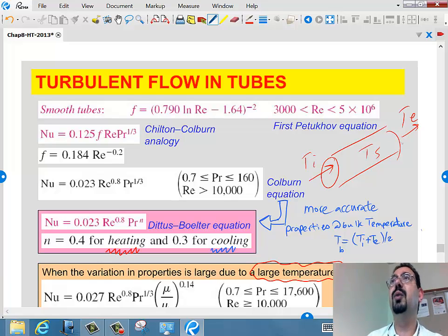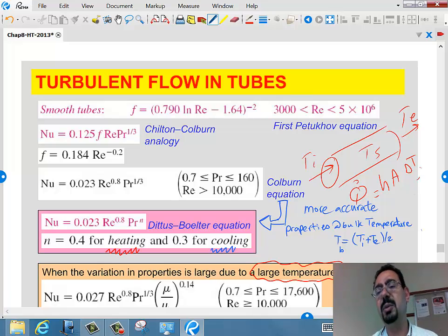or some kind of thing related to the Q, the area of the pipe, the Q, the temperature at the exit of the pipe. It boils down to calculating the flow rate, the heat transfer rate, or Q, which is H A delta T, right? And we talked last time that it should be the logarithmic mean. That's actually more accurate, right, rather than the arithmetic average. It's always more accurate to use the logarithmic mean temperature difference.